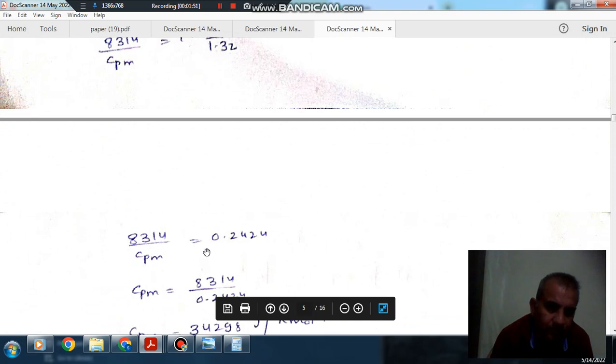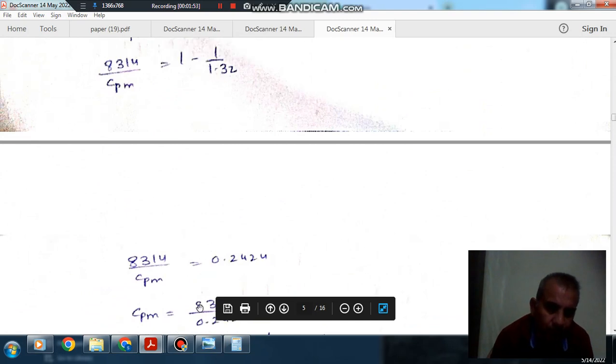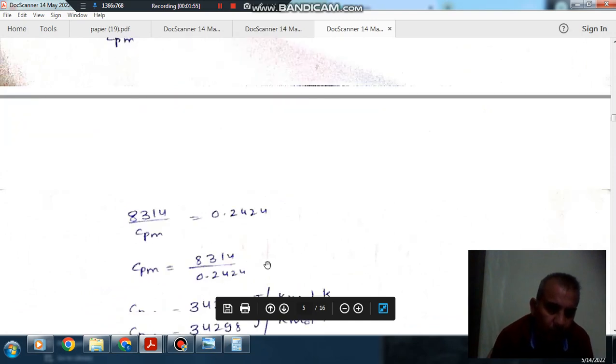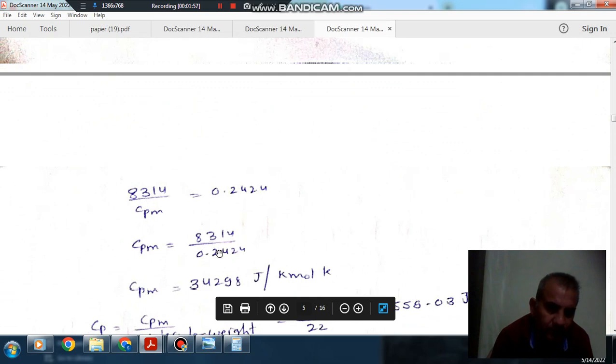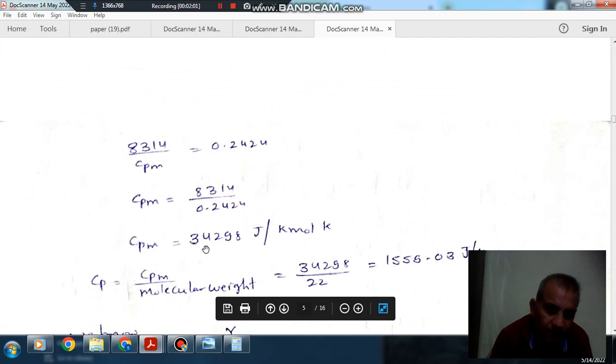So 8314 divided by Cpm will be 0.2424, so Cpm will be 8314 divided by 0.2424, and Cpm will be 34298 joule per kilomole per Kelvin. That is the molar specific heat at constant pressure.